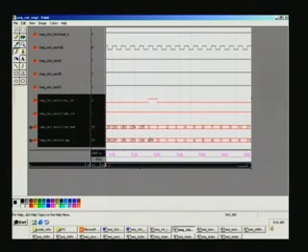When it is 255, this reset counter, which is a combination circuit sensing counter edge equal to 255, which happens right here, immediately goes high, being a combination circuit, and remains so as long as it is 255. Once this is done, this will make the counter 0 on the following positive edge of the clock. That's what you see here, and thereafter it keeps on rolling around and increments from 0 onwards, because it is being reset here.